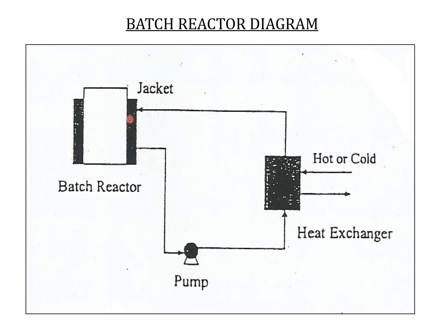So the control will be inside here. The heat exchanger will be controlling the temperature of the jacket, whatever the temperature of this output stream that goes to the jacket, and that is the temperature that you're controlling. It is the manipulated variable to get the profile of temperature inside the batch reactor. Inside this batch reactor, this is quite challenging, quite difficult in some ways. It has to be done very accurately.